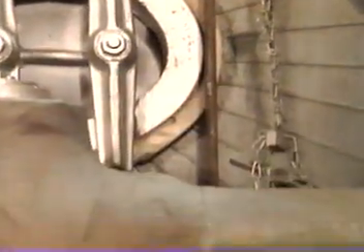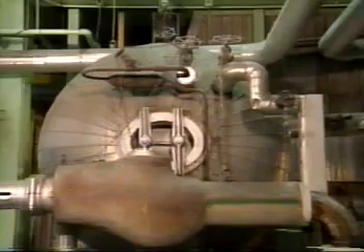Now, the differential pressure determined by the instruments is the difference between the hydrostatic head of the filled column, the reference leg, and the hydrostatic head of the liquid in the vessel. After compensation for the known height of the reference leg and the densities of both fluids, this differential pressure signal is again indicative of only the hydrostatic head or level of the liquid in the vessel.